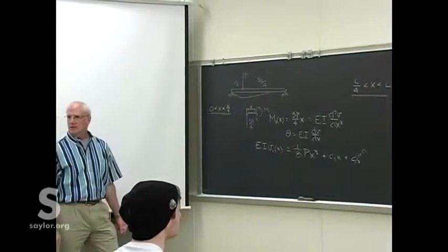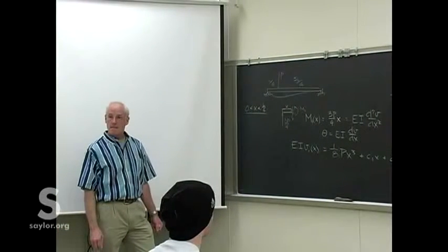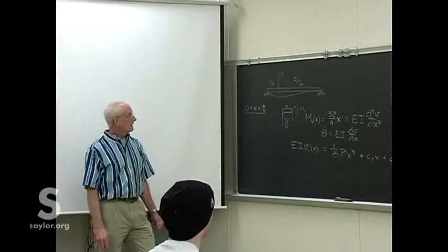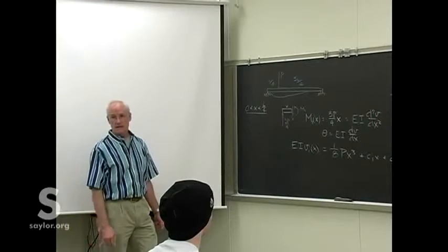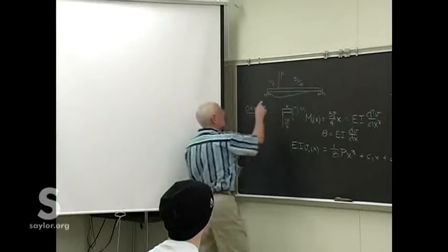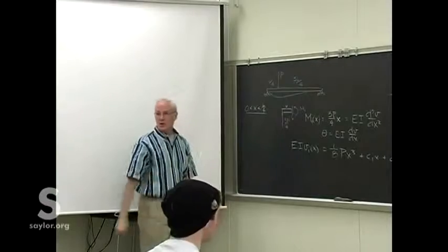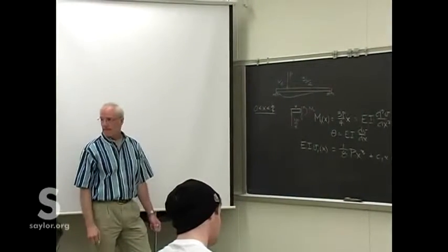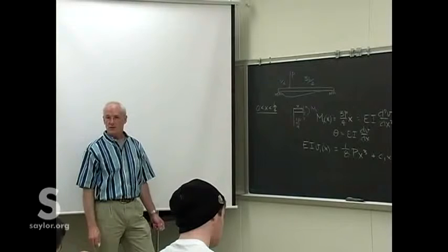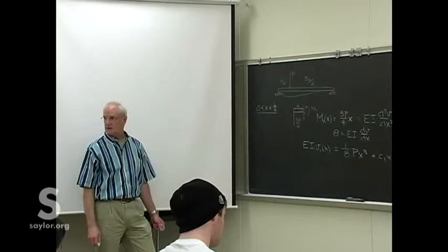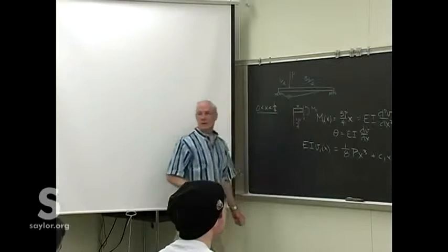What's the other boundary condition? Theta 0 there. What? Is theta 0 there as well? No. It might be, but there's no guarantee. This lowest part of the beam could be right under there, but we're not sure it is. You can't assume it is, nor do we need to. There is another boundary condition that will suffice. And it is a boundary condition at that point.